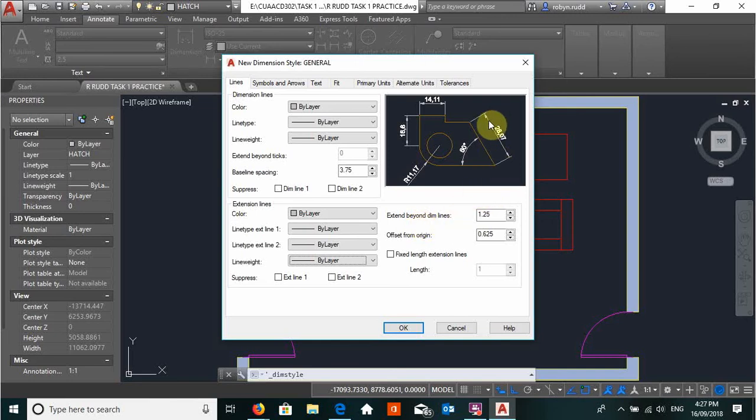You must look at the dimension line, which has got the extension line. So the extension line helps you measure what you are actually dimensioning, and this is the length of that dimension. All right, so extend beyond dimension lines, you're looking at that little extension line there where that little arrow meets that. All right, so it's good to just keep that short and sweet.